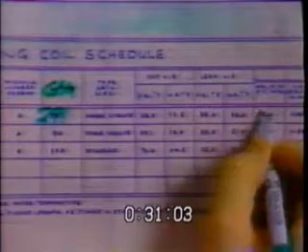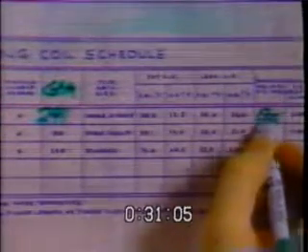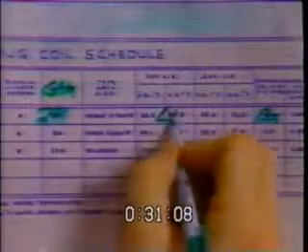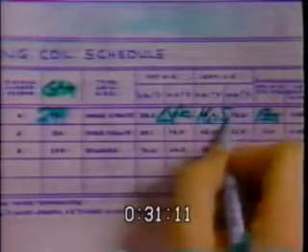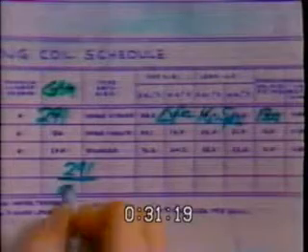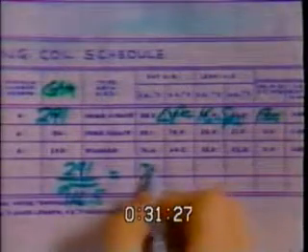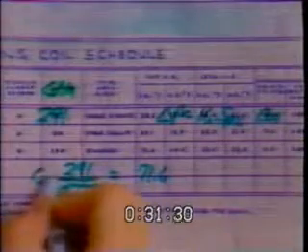Pressure drop is 13 feet. But remember, we had calculated that out to really come out to be a pressure drop equal to 16.5 psi. Now putting that all together, we have 291, which is our gallons per minute. Divide that by the square root of 16.5. You'll come up then with a CV of 71.6. So CV in this example equals 71.6. I would then go to the catalog and find the CV that closely came to this calculated CV.